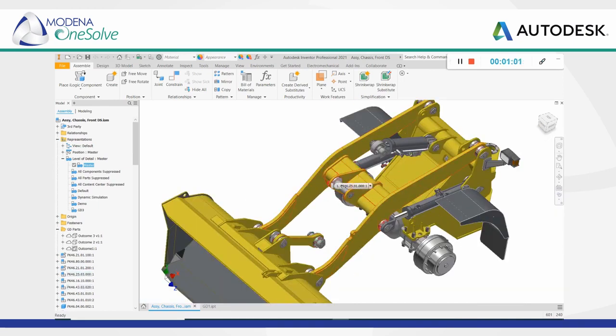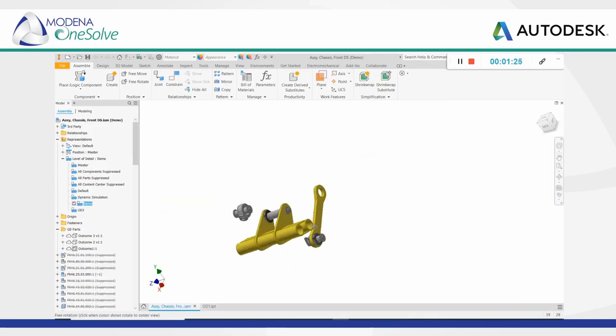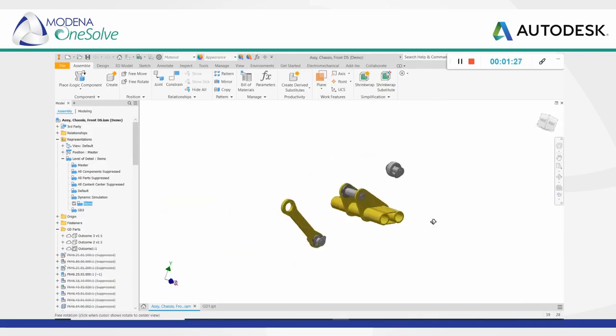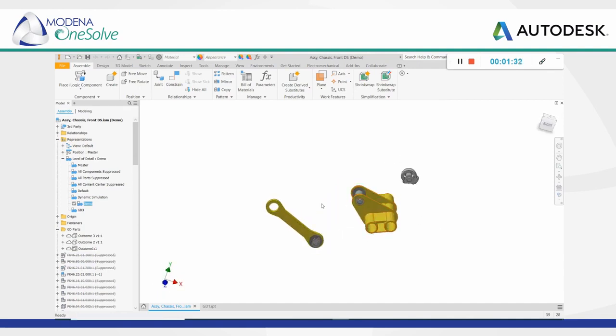Now the next step over here is we've got our assembly. We would like to isolate the key components in order to create the part. So the sub-assembly and maybe any other additional components we may need. And what I've done is created a level of detail of such components. So I'm going to open that up quickly. Once the level of detail is loaded, you can see we have those isolated components on screen. And now we can use this to build the necessary geometry we require to work with generative design.